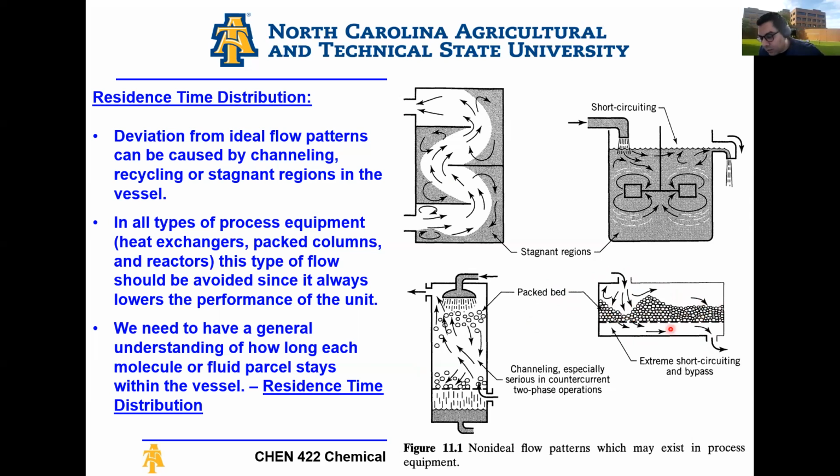So how can you counteract this? There are ways. Maybe I can make this reactor start spinning, right? Spinning disk reactor. This exists. It can solve this problem. Here for a packed bed, maybe I can introduce baffles, have trays, that's why you have trays. You have packing with certain design, which forces the gas not to zip through it. All of these different solutions exist to try and address these problems.